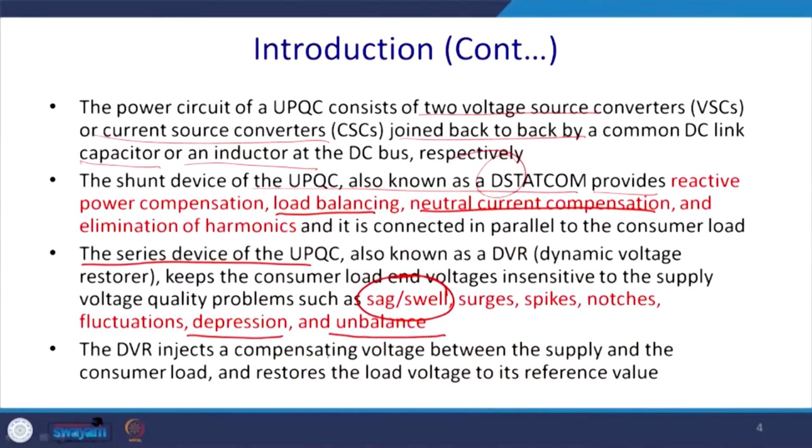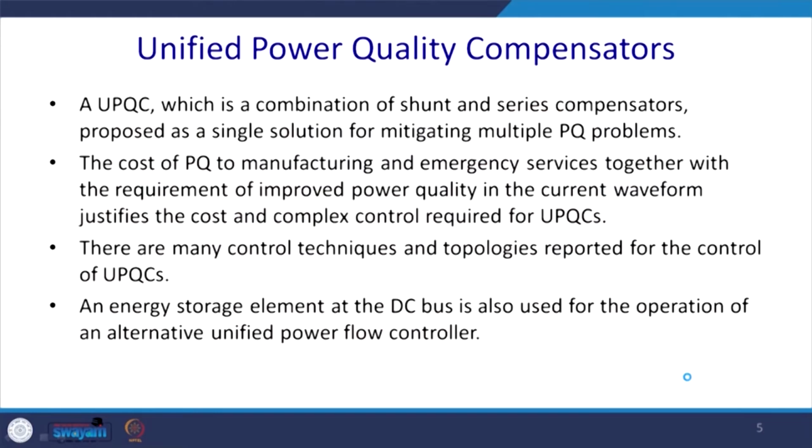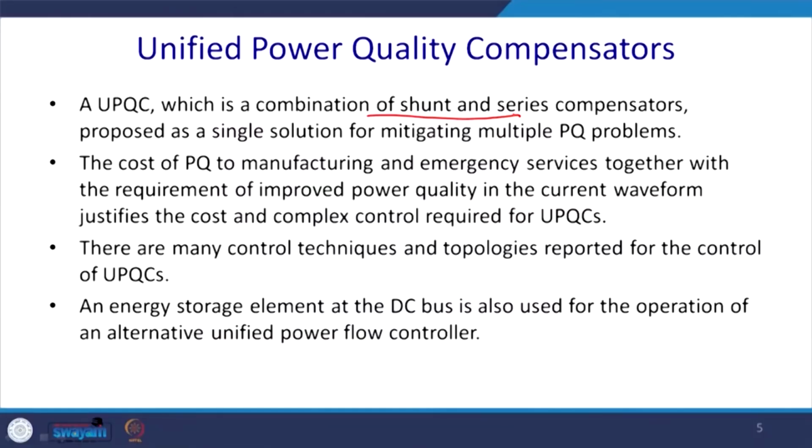The DVR injects a compensating voltage between the supply and the consumer load and restores the load voltage to its reference value. This is the task of the DVR. Now, if you integrate these two entities into a single package, we call it the UPQC. The UPQC, a combination of series and shunt compensators, is proposed as a single solution for mitigating the multiple power quality problems which we have been discussing since the initiation of this course.